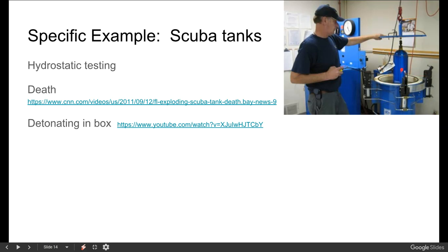One thing that could go wrong with the tank is, let's say it was exposed to extreme heat one day, like in a fire. You took it out, it got cooled down really quickly that night, the metal could get brittle. Somebody one day decided they wanted to do a really long dive and convinced a guy to send it from 3,000 psi to 5,000 and stretch the tank out. You'd never see it by eye. It goes in for its next test, and they go, "Hey, the metal's not moving. It's reached its elastic limit. It will burst if it's refilled." And this is mandatory by law because one of these tanks would kill lots of people if it blew up.